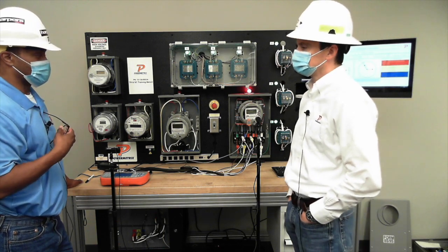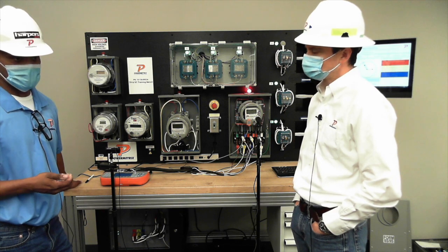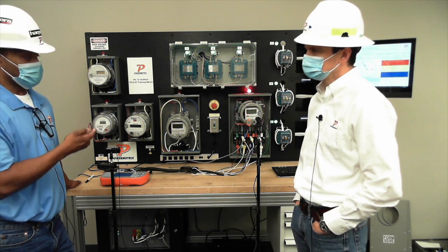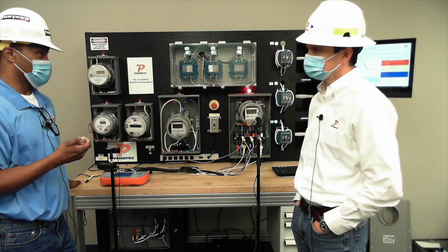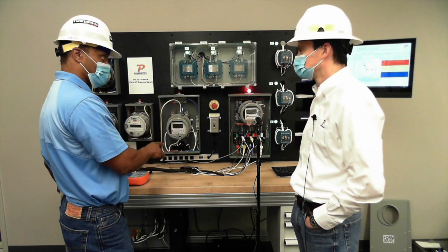So it's a good idea to know that when I went out to test demand meters, I always asked, if it was an electronic meter, what program is in it? If I didn't know, I'd do a line diagnostic hookup with metering software and look in it to see exactly what it's actually measuring.